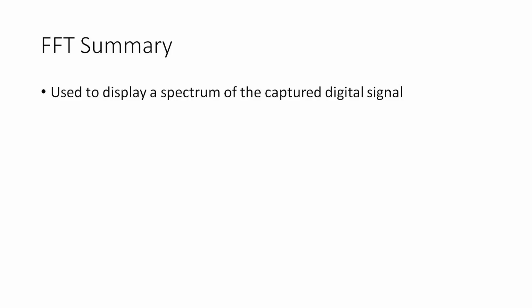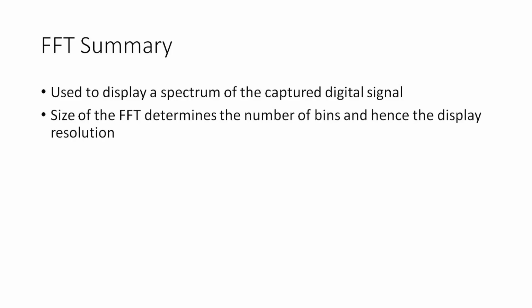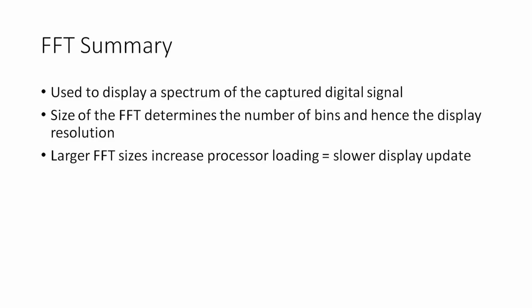So we use the FFT to display the spectrum of the captured signal. The size is determined by the number of bins and the display resolution. Larger FFT sizes increase the load and slow the update rate.